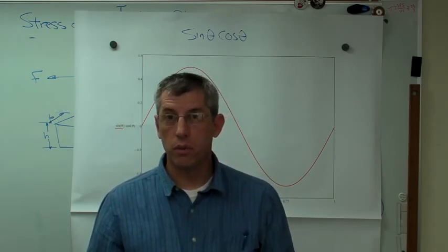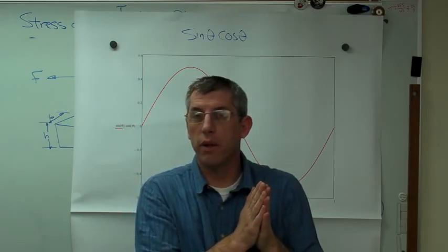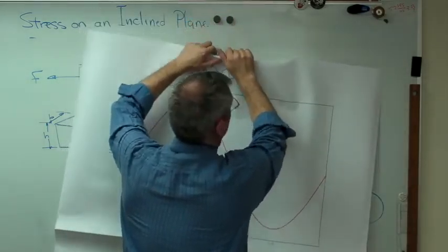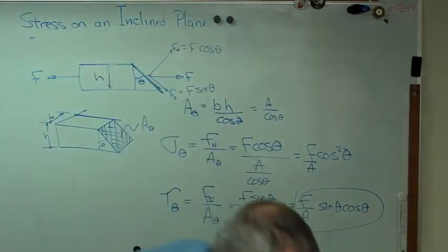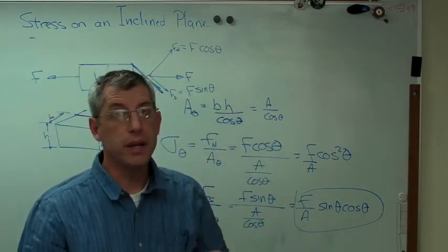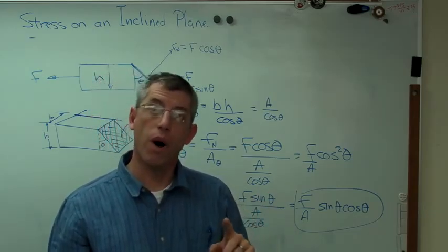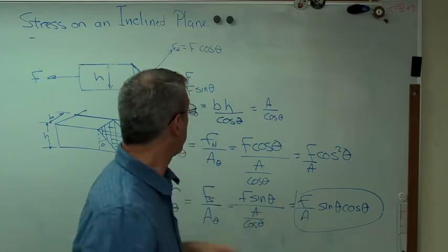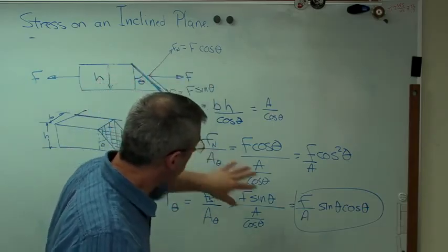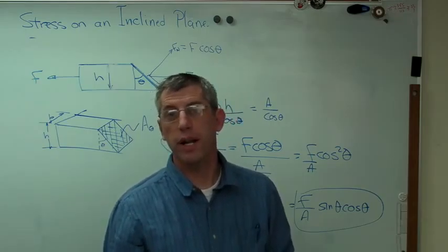By figuring out normal stress and shear stress on a plane, we're at the beginnings of figuring out what's going on with Mohr's circle. Now, what I did here was unidirectional. The force is only going one direction here, so we're not quite at Mohr's circle yet. To get to Mohr's circle, you have to do the general case of a stress element with sigma x, sigma y, and tau xy. We'll do that in another step. But for unidirectional load along the force or stress along a plane, that's how it works. And the maximum is at 45 degrees, or pi over 4 radians. So there you go.